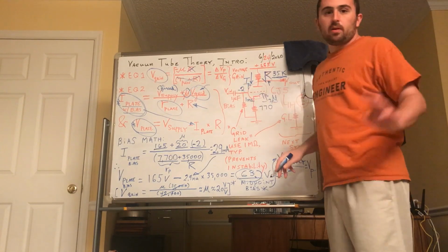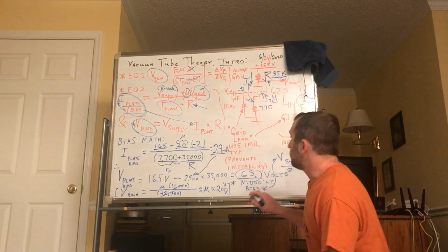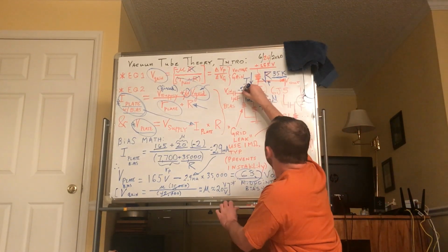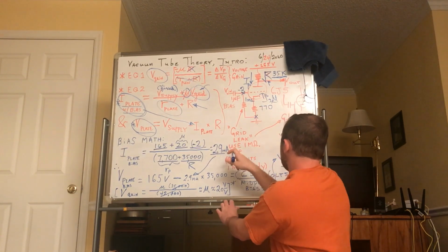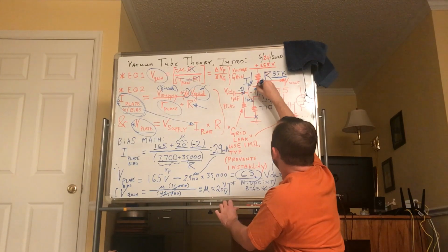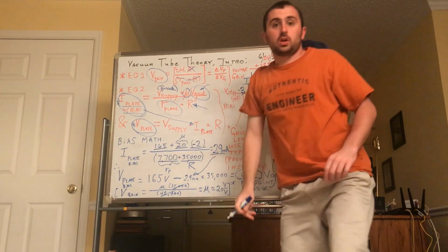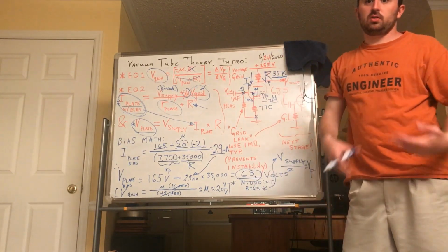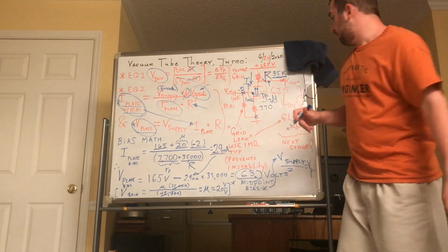And this was done without a battery, using something called self-bias. So let's start this off relatively simply. You put a 1 mega ohm resistor between grid and ground. It's called the grid leak, and it's because occasionally as electrons move across this guy, some of them collide with the grid, and when they do so, they can sometimes stick on the grid. So if the grid was left unconnected to anything, it would turn the tube off because the negative electrons would get stuck on it and repel other electrons from going past it. That's enough theory for the moment.